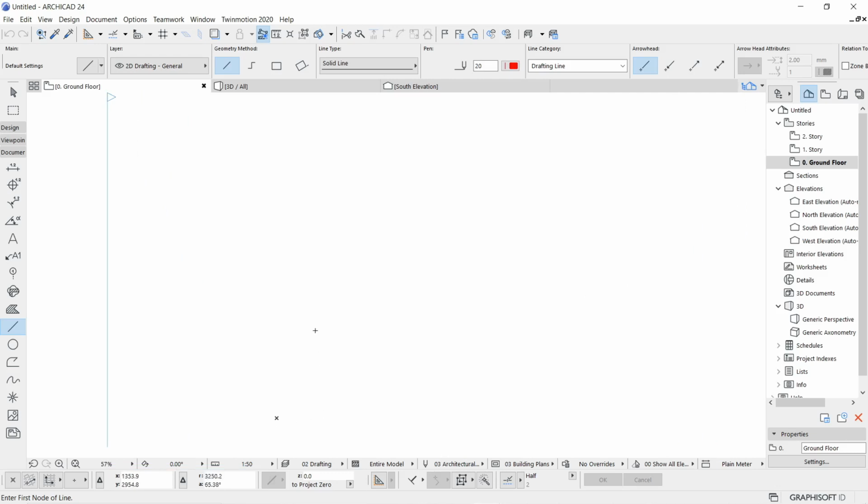Okay, so your mouse is getting displayed with a small plus sign known as a crosshair, and this thick cross sign is the origin point. So that is supposed to be 0, 0 of your coordinate plane. From that you can check out there is an x-axis, which if I travel on the right side, is positive x, negative x on the left side. Same way positive y if I travel upward, or if I travel downward, it is a negative y. And obviously the z-axis is pointing toward you, which is perpendicular to the screen. That's the reason we call this a 2D drafting platform.